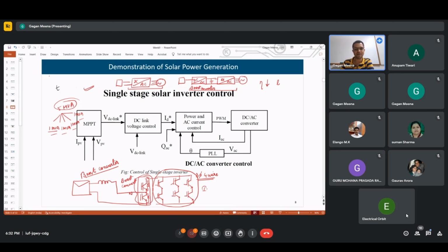It will not increase the system peak load, because what is the use of smart charging if we are increasing the load? We will try to shift the load. We have seen these, peak valley filling, peak shifting. We will try to shift the peak by using these smart charging strategies.